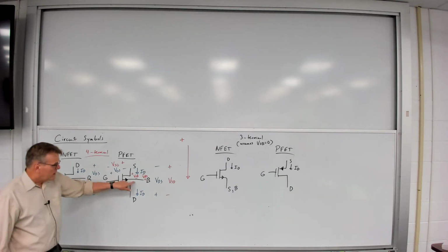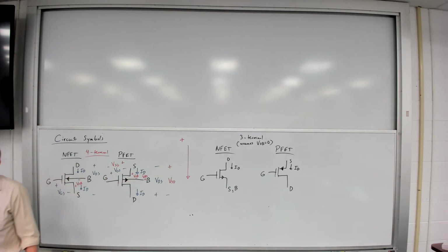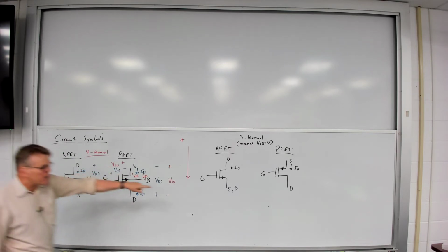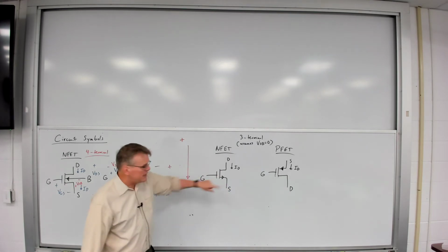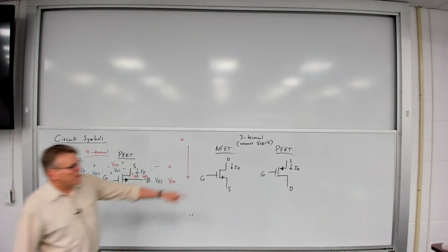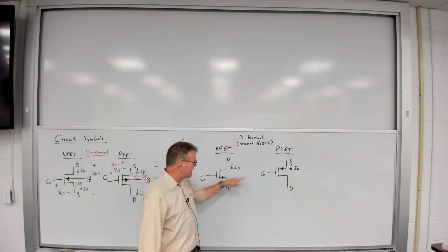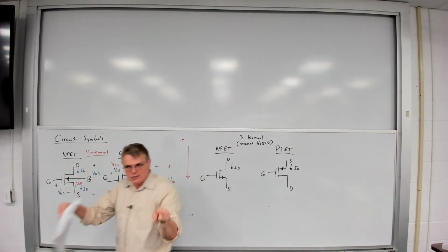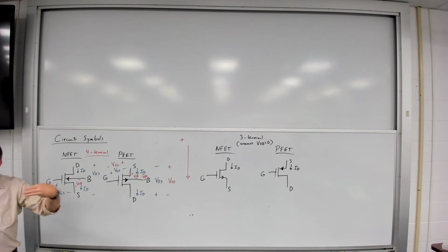Over here, it's an N-well. The bulk is an N-well. The arrow points out. But over here, the arrows flip, which sometimes confuses students, except now the arrow belongs to the source. What is a source in an NFET? It's N-type. What is the source in a PFET? It's P-type. So it points out and in because now it's connected to the diffusions, not to the bulk. Sometimes people get a little confused about this, but once again, pointing out it's N-type, pointing in it's P-type.